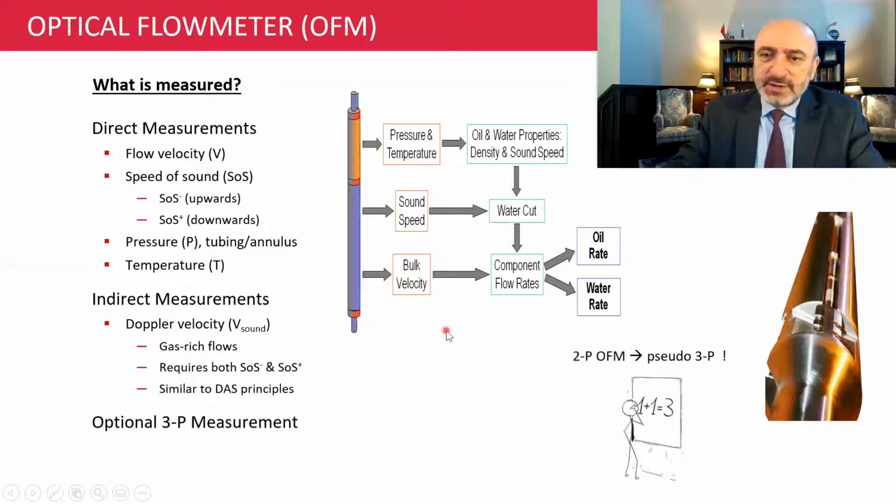So the flow meter at its inline location for this example will be measuring oil and water flow rates. Assume that the pressure at the location of the flow meter is above the bubble point pressure and there is no free gas at the location of the flow meter. So for inline conditions, the flow meter will be measuring water and oil flow rates. However, it will also be reporting standard phase flow rates, and that also means that it will be reporting gas phase flow rates as well.